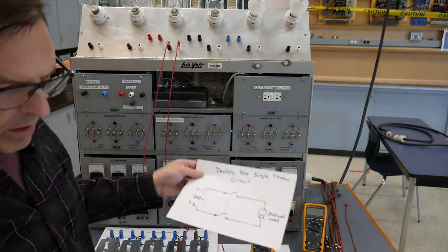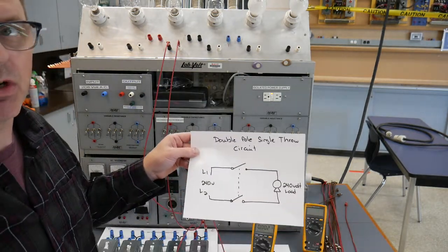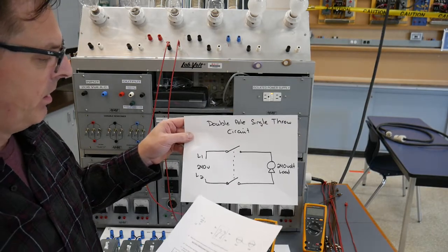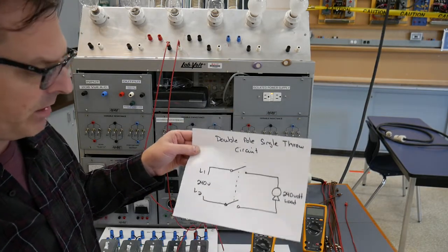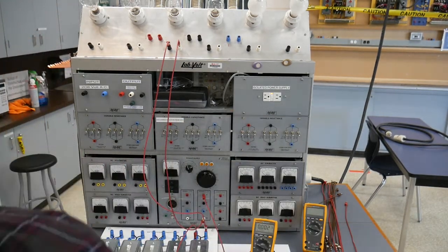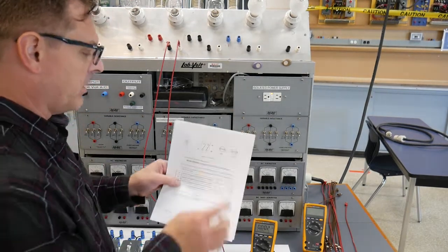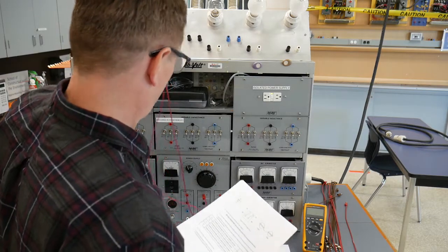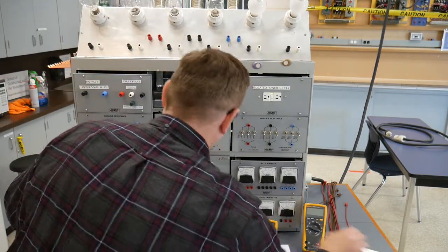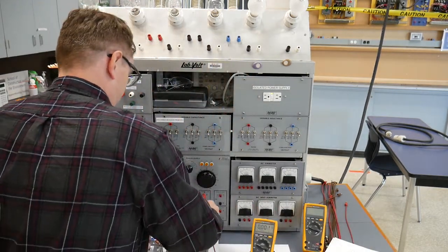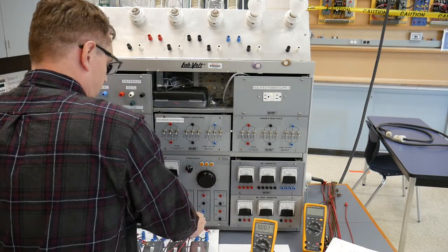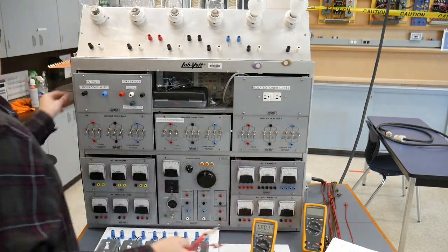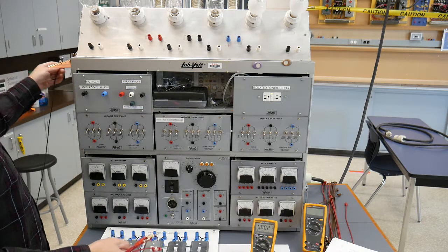Okay, so this one we've got to pay a little bit more attention to because we don't want to have an instance where we have a line-to-line dead short. That would be problematic. So they ask us to connect up 2 cone heaters in this case in series with each other. So that's up top. Just going to undo some of these jumpers here. Just going to grab a short jumper to put in between the cone heaters.